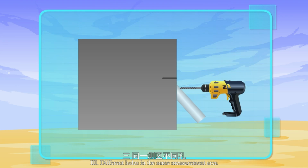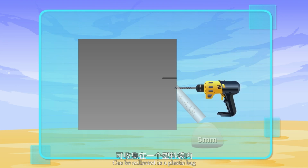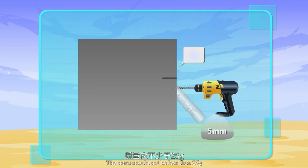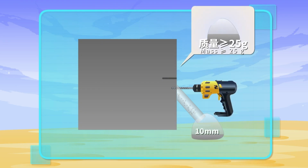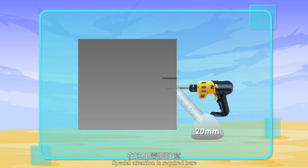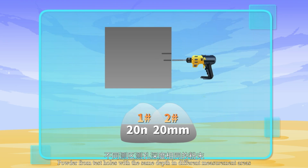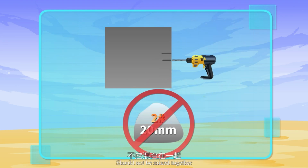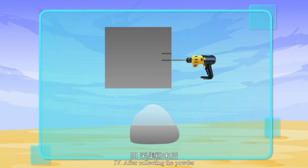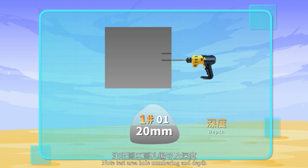3. Different holes in the same measurement area: powder from the same depth can be collected in a plastic bag. The mass should not be less than 25 grams. If insufficient, the number of test holes in the same measurement area can be increased. Special attention is required here: powder from test holes with the same depth in different measurement areas should not be mixed together. 4. After collecting the powder, the plastic bag should be sealed immediately for preservation. Note the test area, hole numbering and depth.